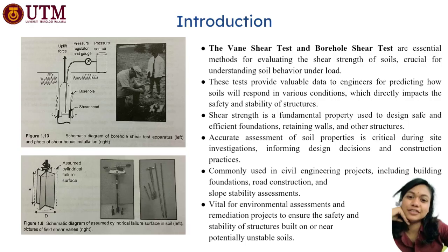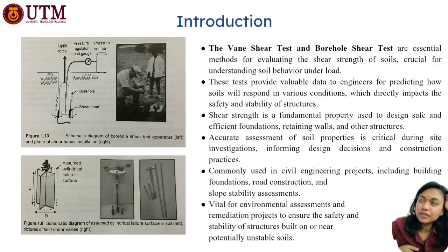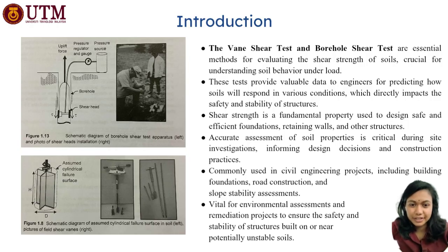Before we enter the introduction, let me explain why the shear strength test is important in geotechnical engineering. Shear strength is the maximum resistance that soil can offer before it fails along its interior surfaces. It controls the stability of foundations, slopes, retaining walls, and embankments. Most soil failures in engineering projects happen due to shear, not compression or tension.